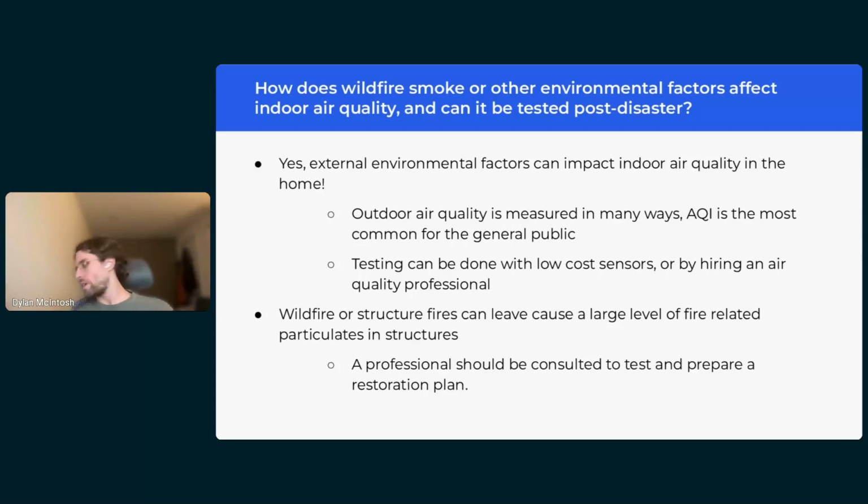When you have penetrations right here, I've got an electrical outlet, things like that. Those are pathways that mold spores could be released from. It's not always going to be the case. There are ways to take more specialized inside of wall samples by drilling a hole or entering in through one of those penetrations, like I mentioned, an electrical outlet cover, things like that.